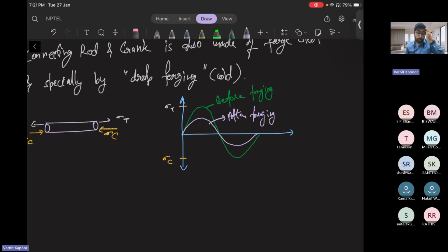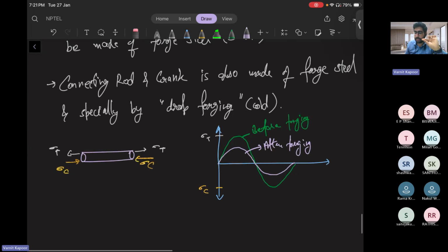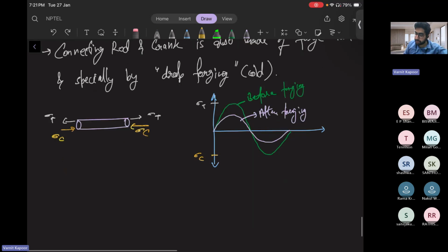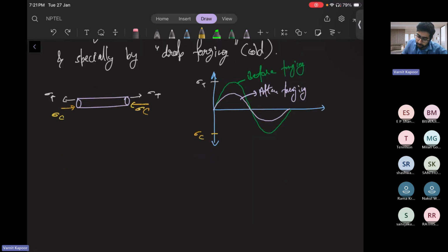Okay. So this is nothing but your fatigue loading condition or reversible cyclic loading condition, what I've written, where the crack propagation rate is infinite. If a small crack comes inside the pin, you can imagine that under very high stress scenarios, this can immediately damage the whole pin, and your whole engine piston cylinder arrangement will be damaged. So the crack propagation rate is very high here in the fatigue loading condition.